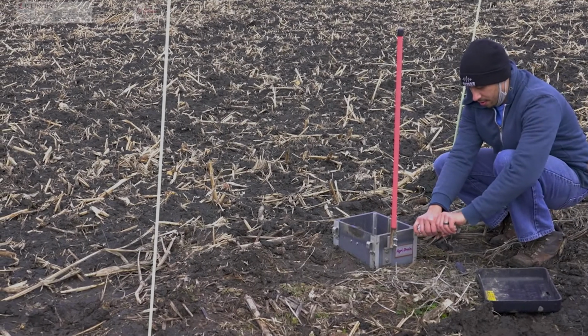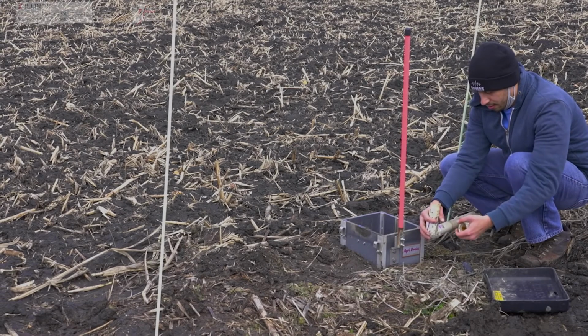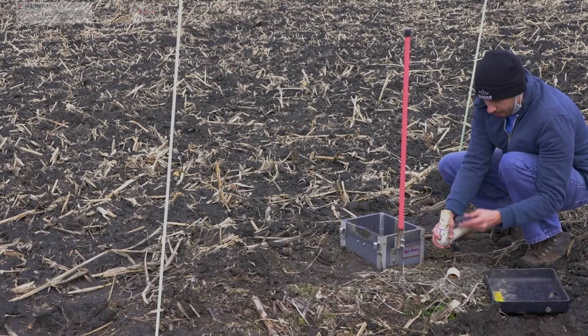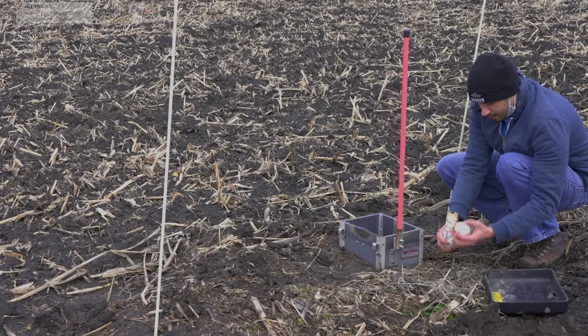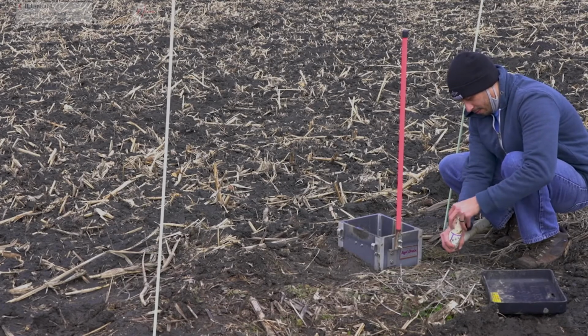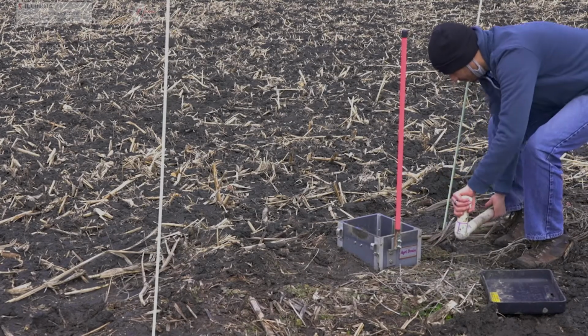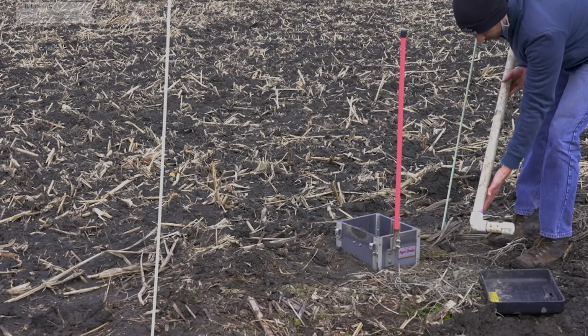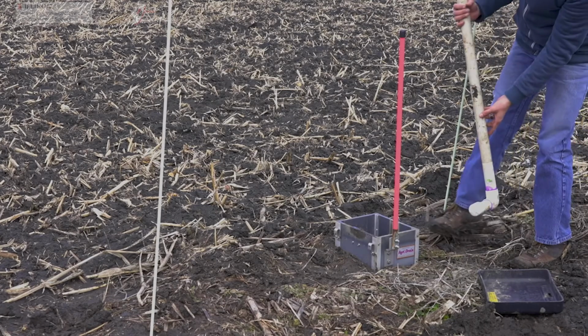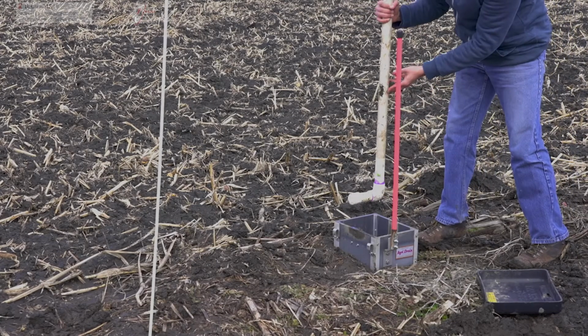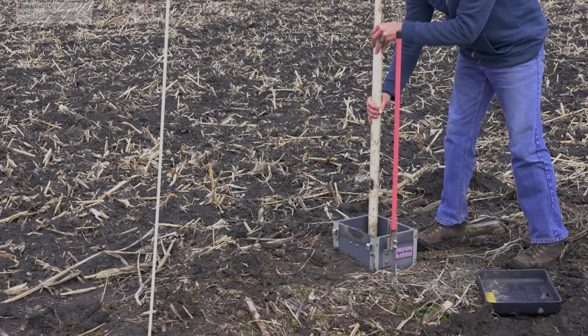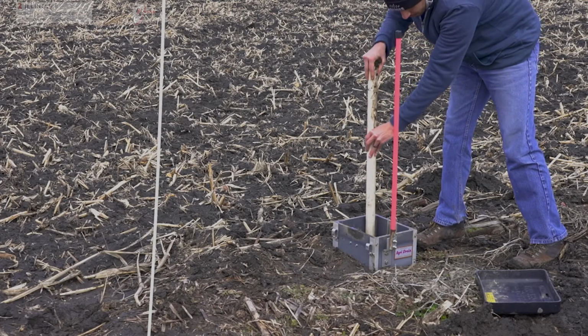Once the PVC elbow has been assembled, put the sensor inside and screw the cap on. These PVC deployment sticks ensure that the water sensors lay flat and level at the bottom of the control structures. Remember, the water sensors are simply logging the depth of water pushing down on them, so if the water sensor moves or isn't laying flat on the bottom of the structure, you'll get an incorrect water depth reading.